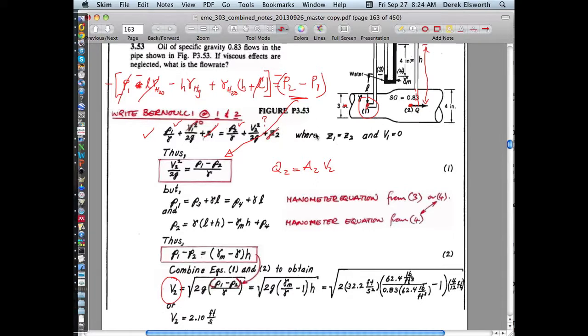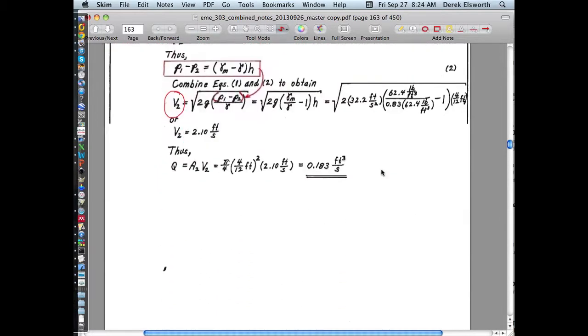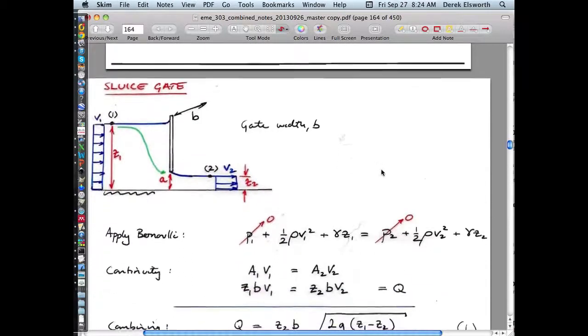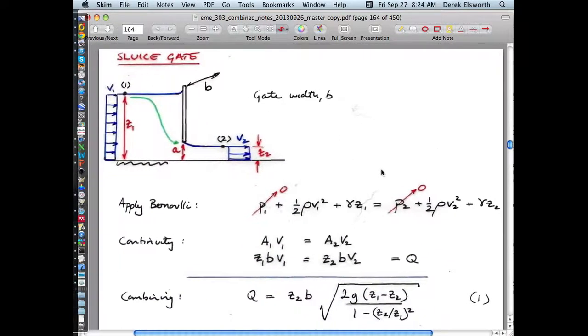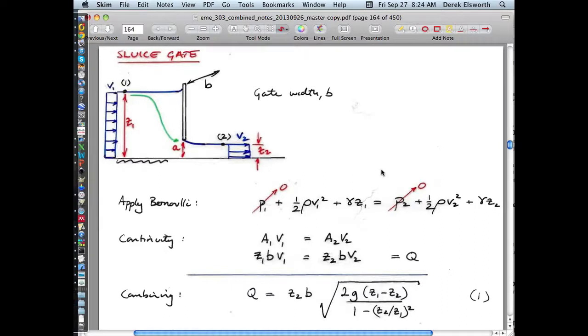So if you write the continuity equation as area 1, velocity 1, density 1 equals area 2, velocity 2, density 2, then you're conserving mass between upstream and downstream. So it could be compressible. The continuity equation can apply to compressible flows as well. But as we've seen, we've applied Bernoulli to air, which is compressible. You know, the cyclist is really a compressible fluid. So you won't have to make that decision in the things you do. You can apply it to compressible fluids so long as the pressure changes aren't so great, I guess is the issue. Okay? So flow in pipes.